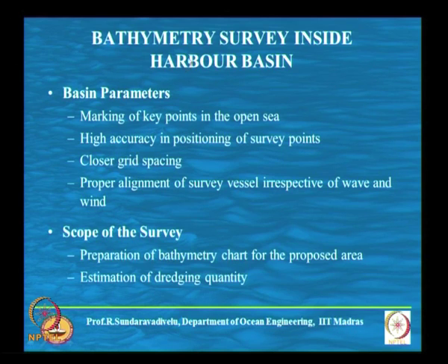Let me spend some more time on this. There are 2 types of bathymetric survey required. One survey is required once the port is commissioned, another survey is required for greenfield ports. I have some examples which I will show you later. So once you establish a port and you want to do a survey in a harbor basin, you have to mark key points in the open sea. High accuracy is required in positioning of the survey points. You need closer grid spacing. Grid spacing means the interval at which you find out the depth. To be simple, bathymetric survey means you have to find out the water depth at different locations.